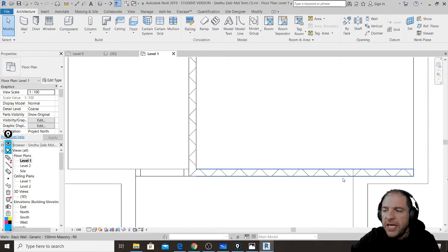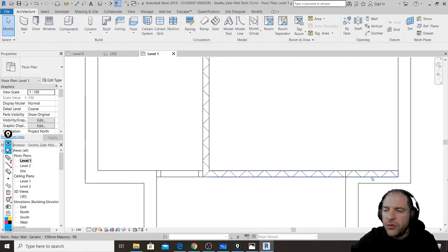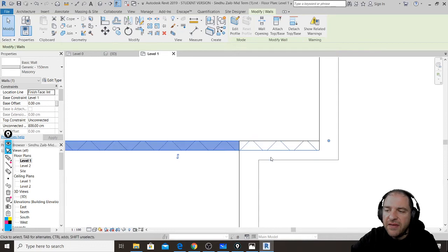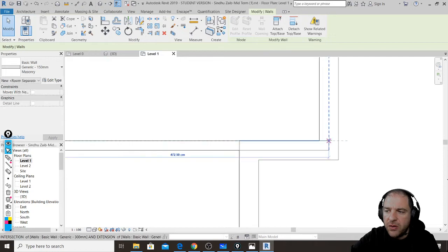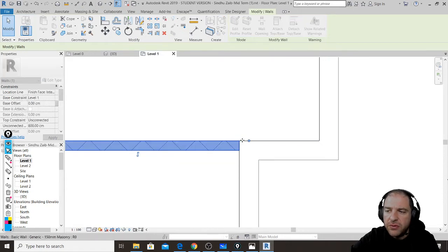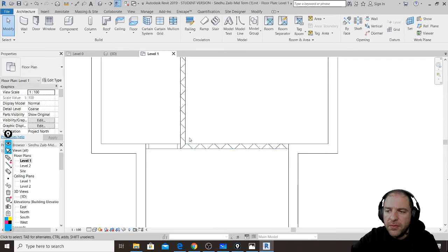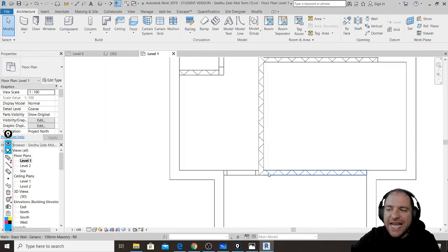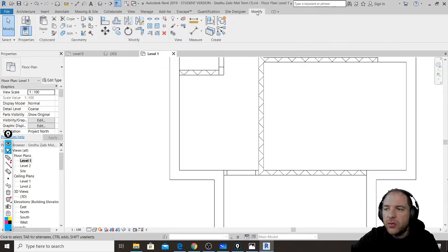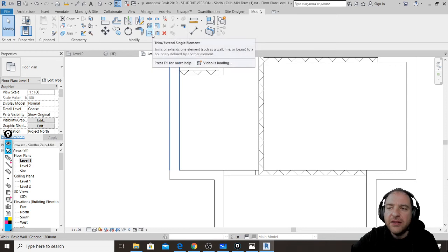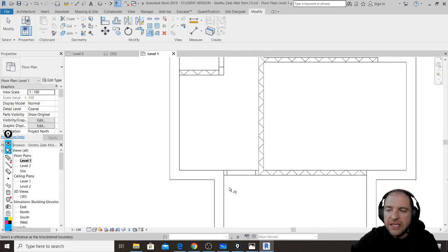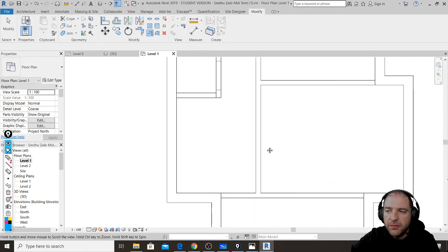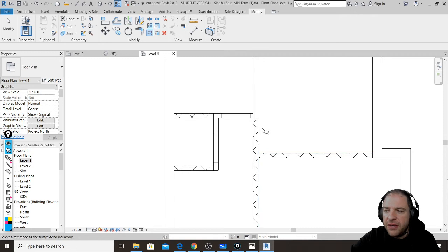So look, in here, what I have to do is, I can see that by picking the entire line, my wall is going inside the existing one. So I will select the vertex and I will drag it here. I will instead extend this wall till it touches this one. So I go to Modify, Extend Single Element. I want to extend it till here, and I extend this one. Here is fine, here is fine.